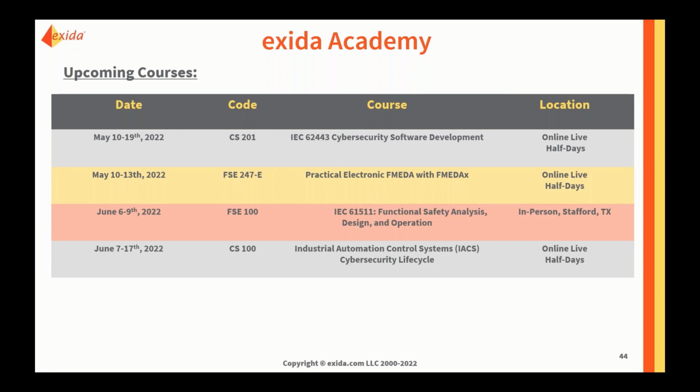Is it in continuous control, and that is the safety action that it needs to carry out, in which case, yes, PFH controls its behavior, or it might be a basic control safety function that is not SIL rated, that could be rarely demanded in the instance of other failures or rare demands on that control function, in which case it's a protection layer and PFD defines its performance. So it's really down to an understanding of the exact situation that you're looking at.